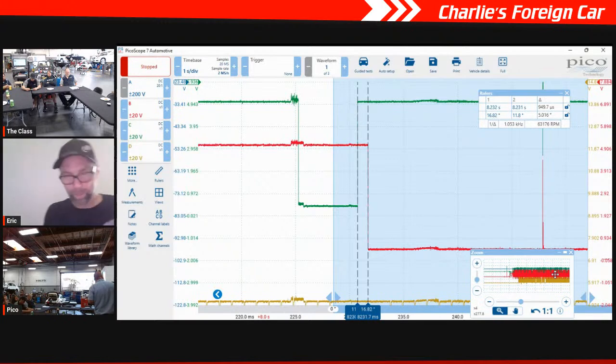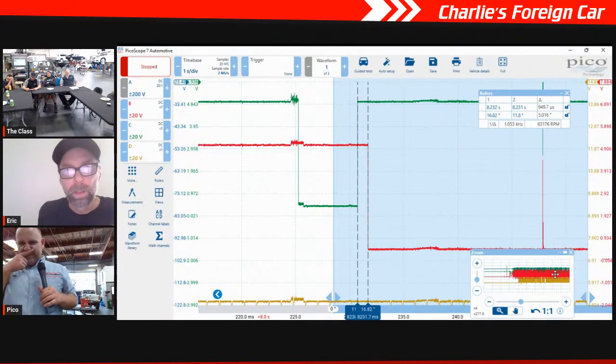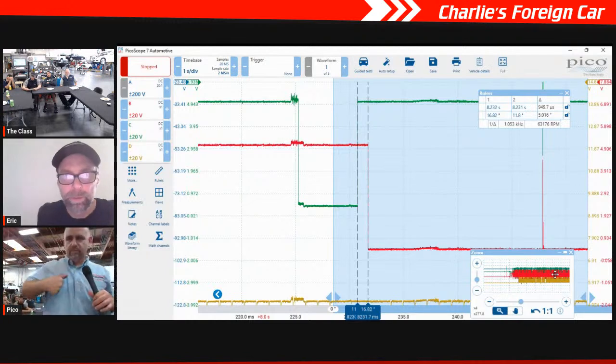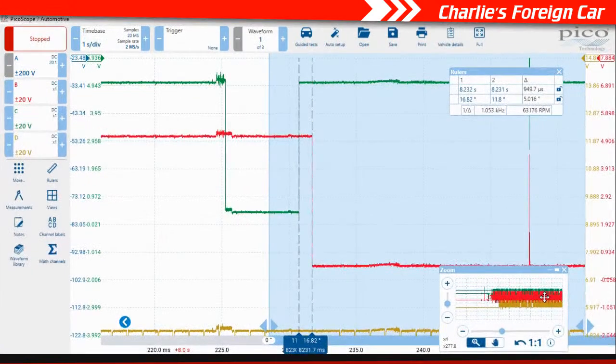All right, and what does the scan data say as far as its position? That's where we were. Yeah, sorry, I stopped you because you had the car running. Go ahead and fire it up. You could look at that advance. You do the same with the timing advance too, since you have an ignition mark on there, just as a cross reference. All right, so the intake cam right now is 42 degrees, 42 degrees of crank angle.